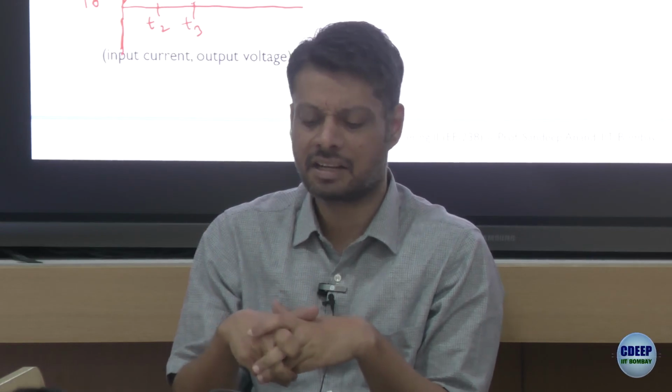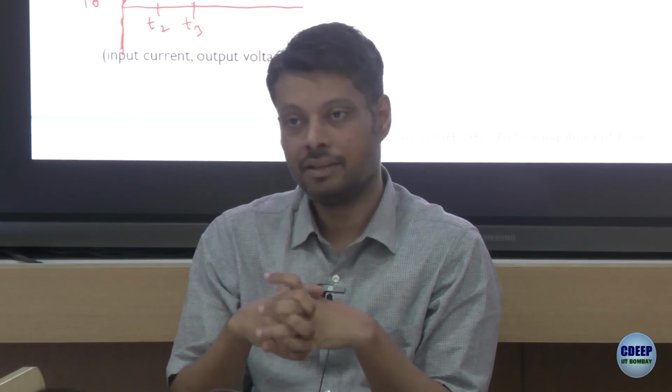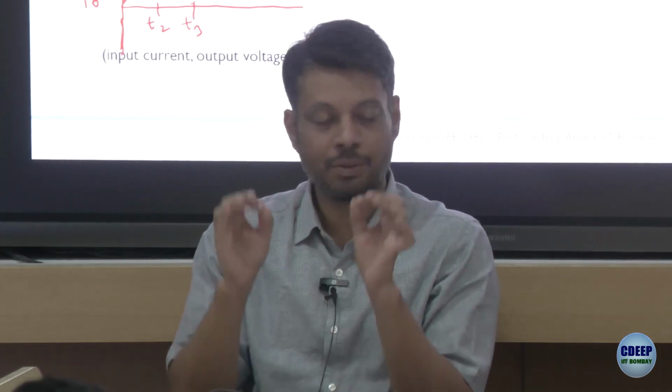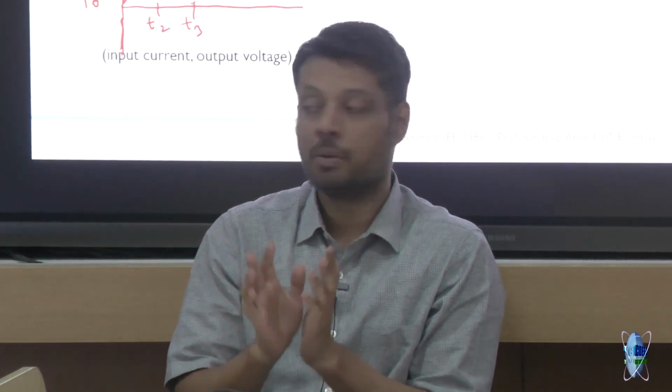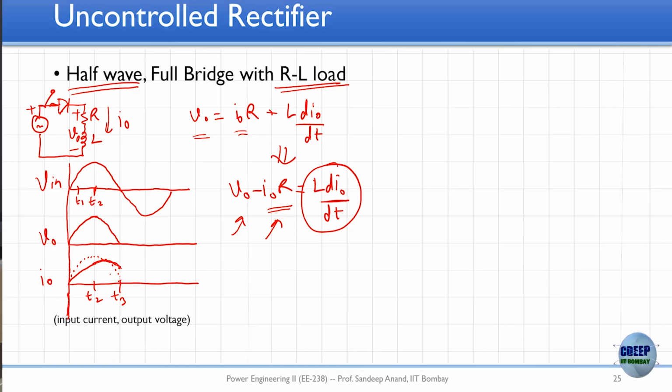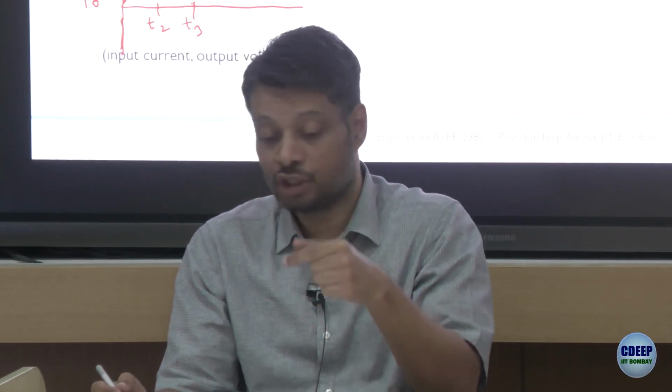Let's try to apply that. Let's assume that the inductor current suddenly becomes 0. The diode turns off, hypothetically. Okay? Hypothetically assume the diode turns off at t equal to T3, and the current suddenly drops from whatever the value was to 0. What will be di/dt? di/dt will be infinity, and with this polarity, V equals L di/dt, minus infinity. That means the top point of the inductor will be at minus infinity with respect to the negative point. So the negative point will be at a very large potential with respect to the positive point in this inductor.